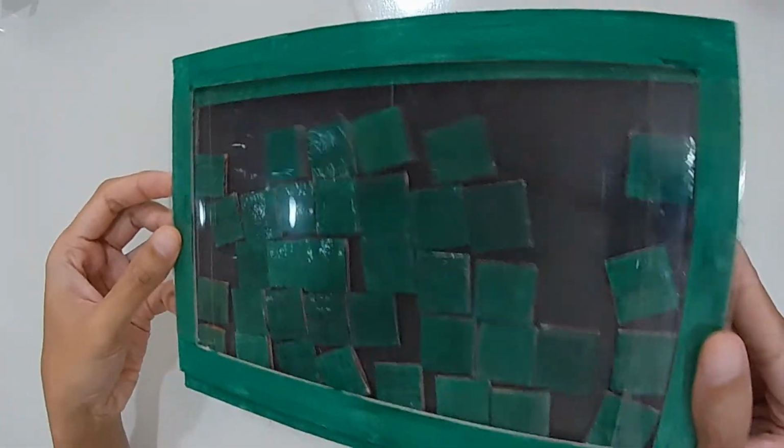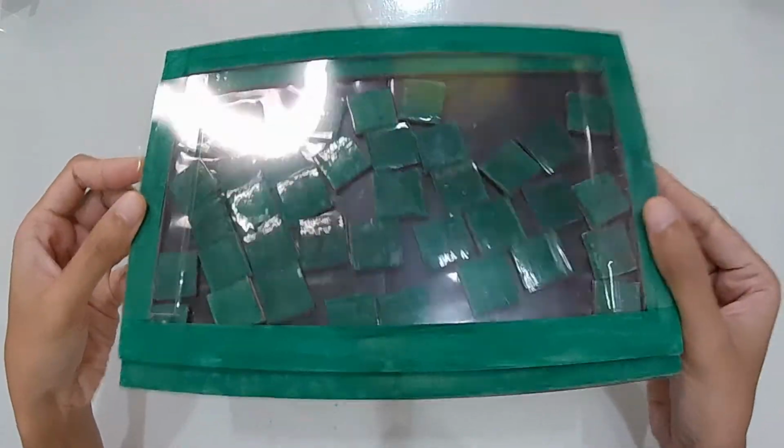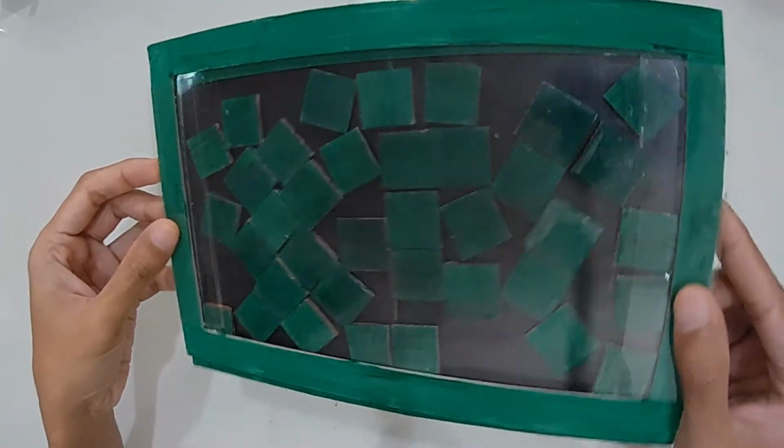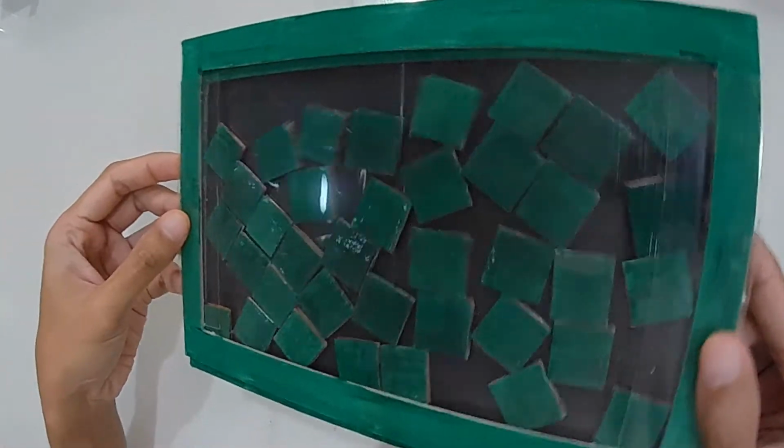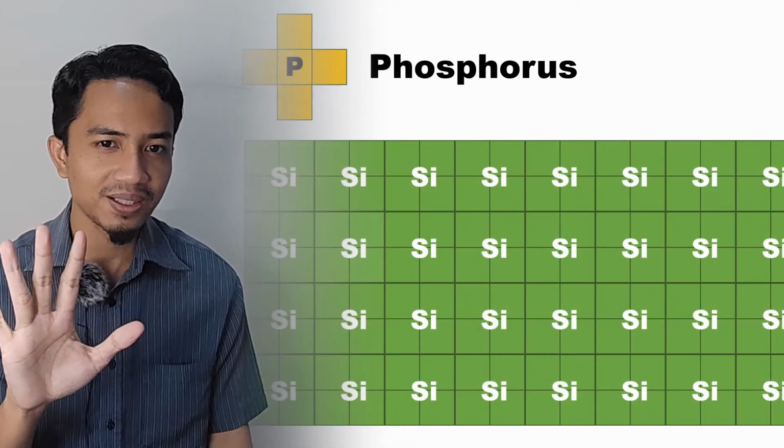But it is much slower than free electrons because we need to move through the hole locations that exist inside the material or inside the bonding. So how do we make it faster? We need free electrons. How do we add free electrons to the material without burning the material? To create free electrons, we add donor dopants or donor atoms to the silicon. The silicon is doped with phosphorus, which has 5 valence electrons.